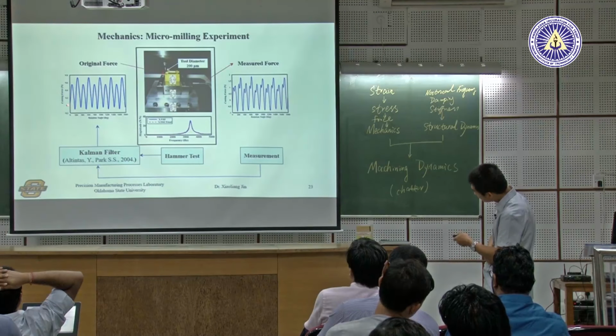So you take the force output from that and then do the FFT of the force, is it? Yes, yes. But you know that the natural frequency for this thing is about 4 kilohertz, 4.4 kilohertz. That's what they claim. But usually it's less than that. How much are you getting? This one is 3.5 at peak.